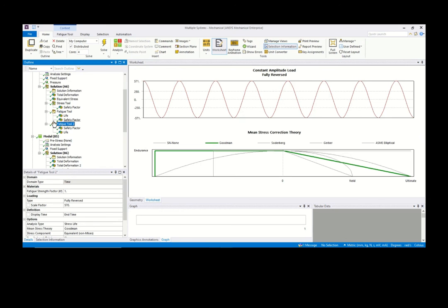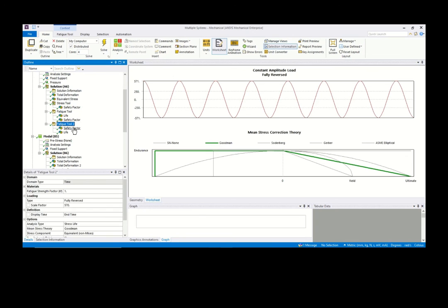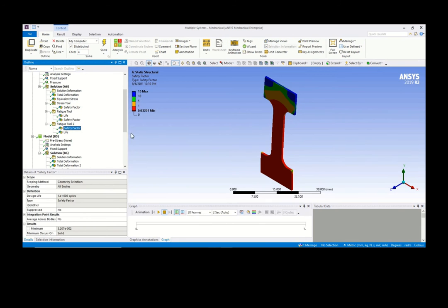So if you revisit this fatigue analysis again, you can scale it by 570 times. This completely reverses the 570 times of your equivalent stress of 4.7. Then you can find out that the safety factor is no longer more than 15. It's only 0.03.